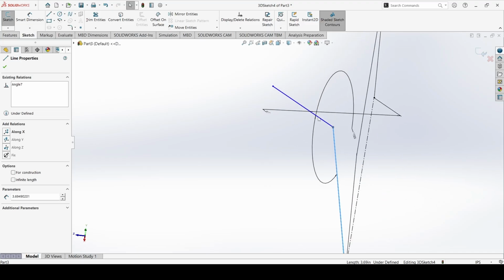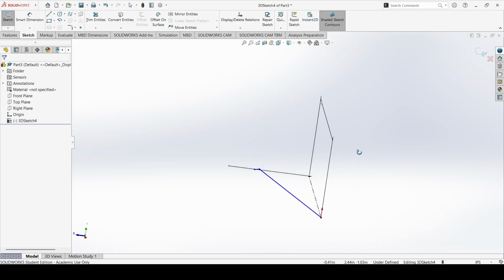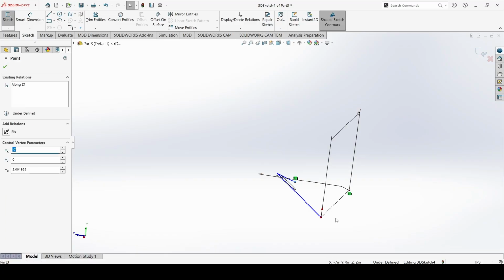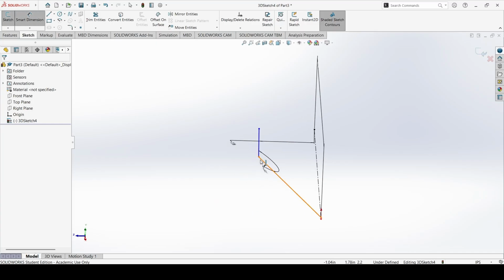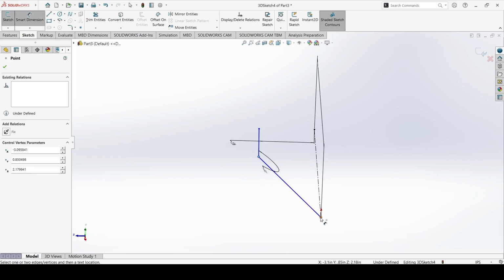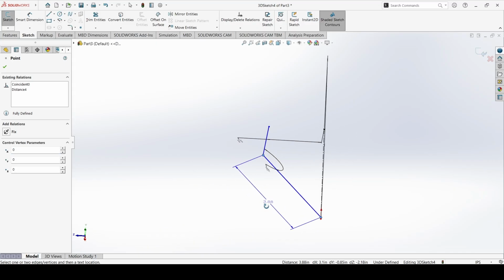Once again, it's still 2 inches away, but we need some more constraints to make sure this is where we want it to be. So if this is where it's at, and this is where it's at, or those are the two constraining points, we can create a smart dimension. And so let's say we want this to be a certain distance away from here. Notice how all we get is a length there. And while that might be helpful in some applications, we want the z distance from here to here.